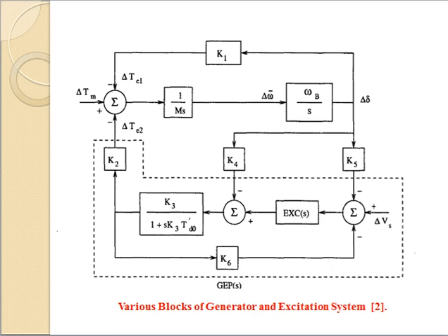Now this is not the point of discussion for this particular lecture. This will be covered in our lecture series in another lecture, which is called analysis of synchronous machine. But when you are dealing with your excitation system and power system stabilizers, you may neglect rotor dynamics, because our focus is mainly on voltage and what is the impact of oscillations, and you want to damp these oscillations. So let us, for the sake of time, neglect rotor dynamics.